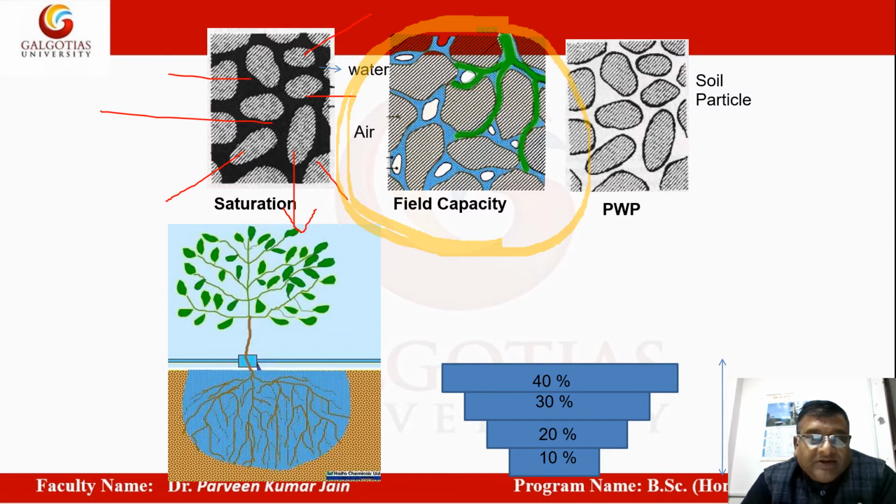So, as an agricultural engineer or an agronomist, we have to think about the technology in which we can have this field capacity situation throughout. That is the theory behind drip irrigation, and with the help of drip irrigation technology it is possible to maintain that kind of water in the soil, so that your soil remains at field capacity throughout the growing season.